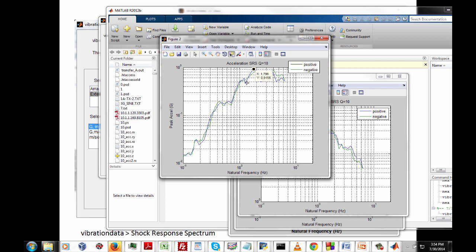And that hint is, if we want to minimize the absolute acceleration of that building, or maybe a piece of equipment in that building, or some structure, we should have the least possible natural frequency. Because the lower the natural frequency, the more isolated our system is, and we essentially attenuate the acceleration and achieve a very desired result of minimizing the response acceleration.